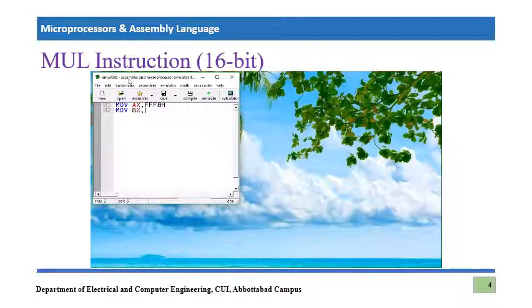Next, the other 16-bit number is F257 hex, and we're going to multiply them, MUL bx. Both are 16-bit numbers, so the result should be 32-bit. The result cannot be stored only in AX because AX is 16-bit, so we need an extra register here, and that would be DX. So let's see the result.